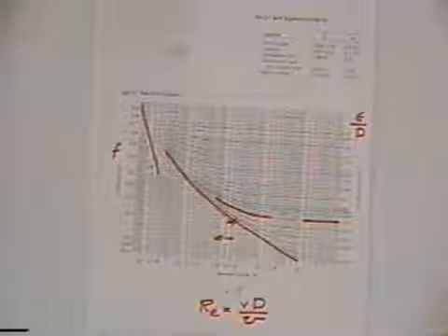Okay, so the different concepts of flow head losses are reflected in this diagram, and it also provides a mechanism so that when you've got problems to solve and you need the friction factor, you can just read the friction factors off the diagram. And the diagram is included in the reference manual, so it's readily available to you for the exam.